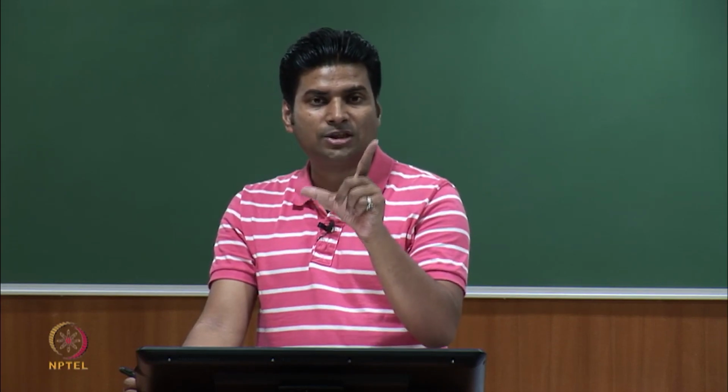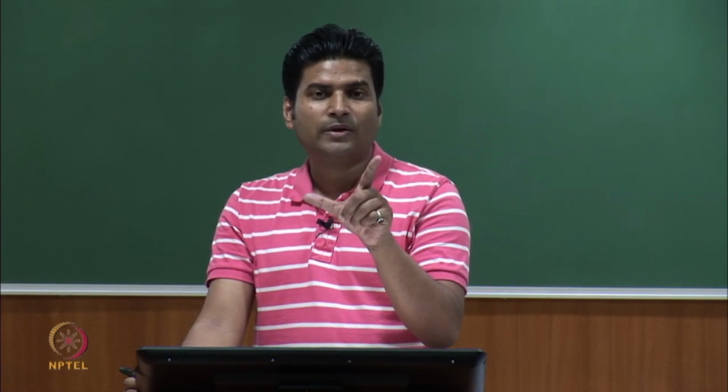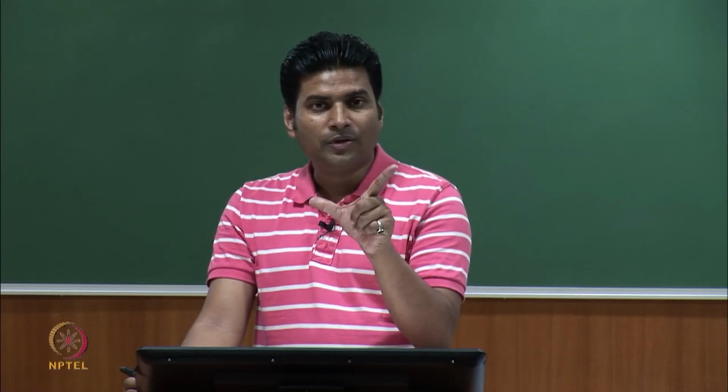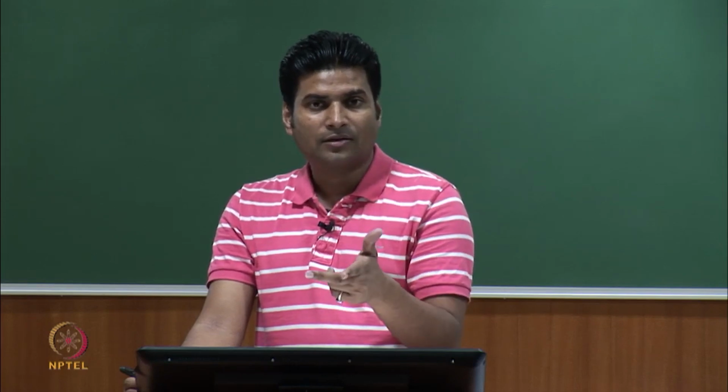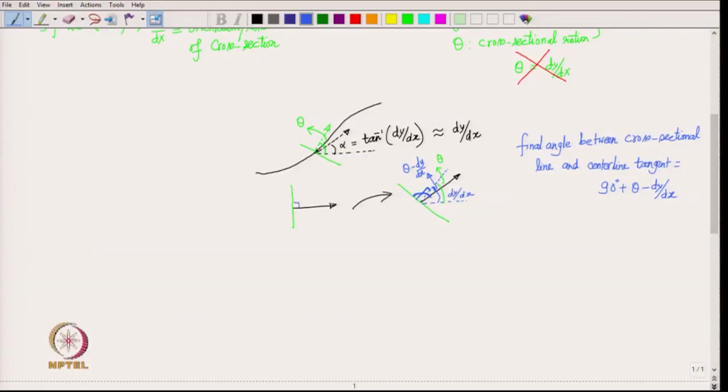So, what can you say about the shear when those two lines are concerned? Shear will be negative, because shear reduces the angle and here the angle has increased. So, shear here would be the negative of the change in angle. And what shear is this? You see, this is the x axis and that is your y axis, because your beam would initially be like this, and the axis is the x axis and then the perpendicular is your y axis.